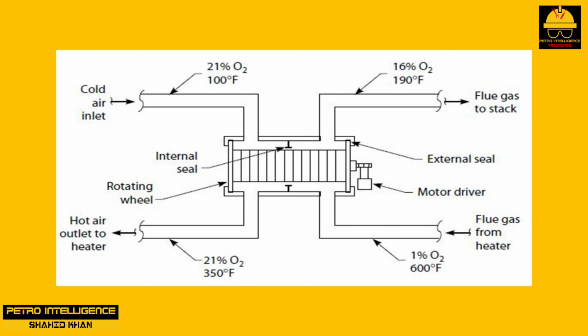All air preheaters are subject to corrosive attack caused by condensation of sulfur trioxide. At 150 ppm sulfur in the fuel gas, operating experience shows that a minimum temperature of 350 to 400 degrees Fahrenheit minimizes corrosive attack. Uneven cooling in the preheater results in the need to keep the flue gas outlet temperature 50 to 100 degrees Fahrenheit above the calculated SO3 dew point. The flue gas outlet temperature can be increased by use of an air preheater airside bypass, or by increasing the excess air in the firebox.